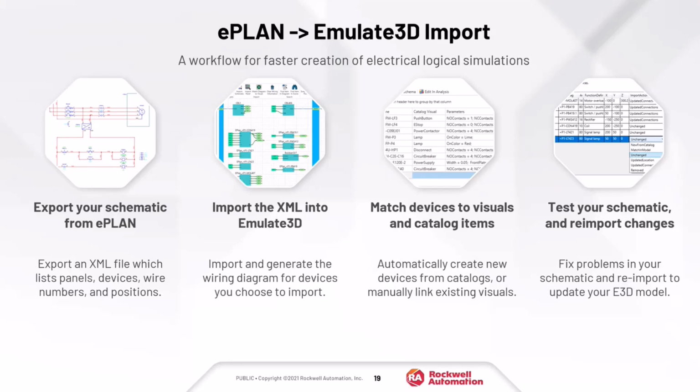One of the challenges of creating simulation models, and it's true for various different simulation tools, is the time it takes to create those models. The mechanical aspect can be imported from any CAD tool. If you have Autodesk Inventor, SolidWorks, CATIA, whatever, you import the 3D models. But now you have to make those 3D models move. So you have to substitute certain blocks or give them some movements. You also have to give them the logical dependencies, meaning that if I press this push button, this motor needs to go on. If I hit this stop button, this motor needs to stop.